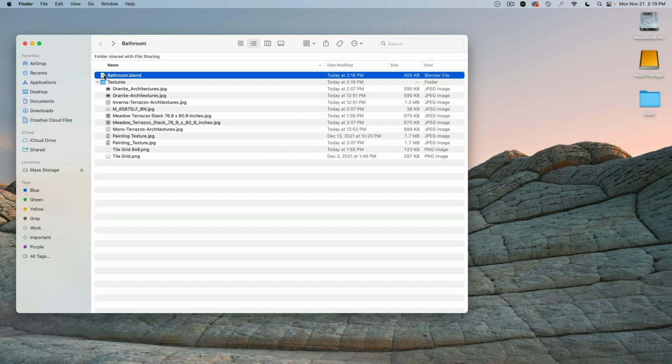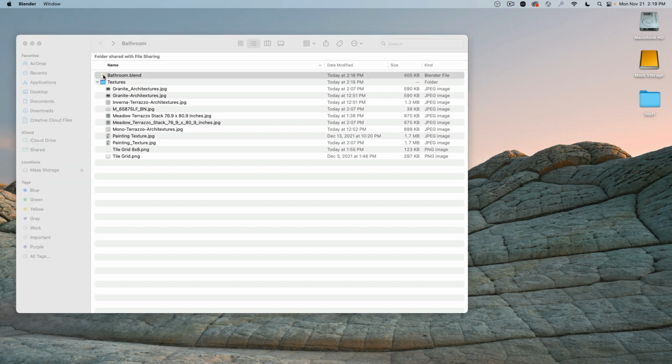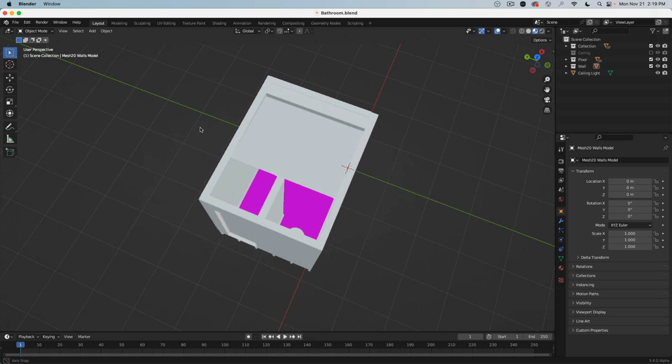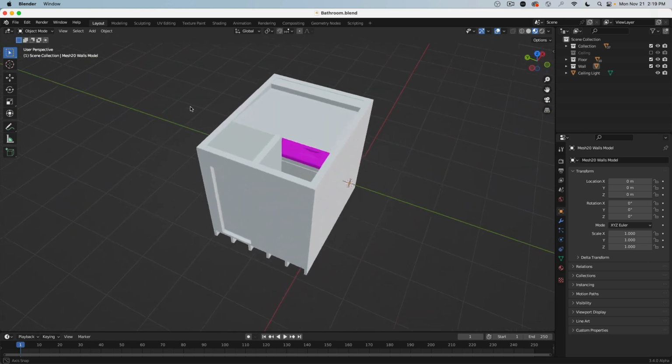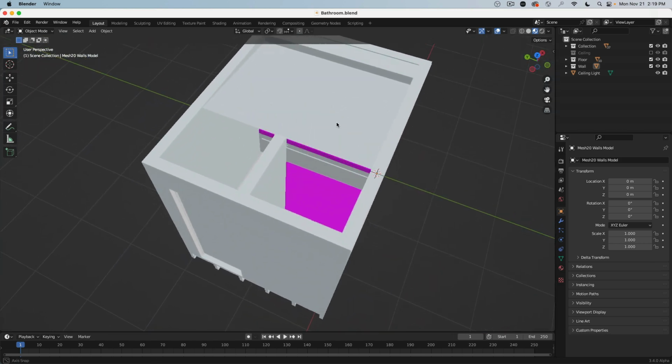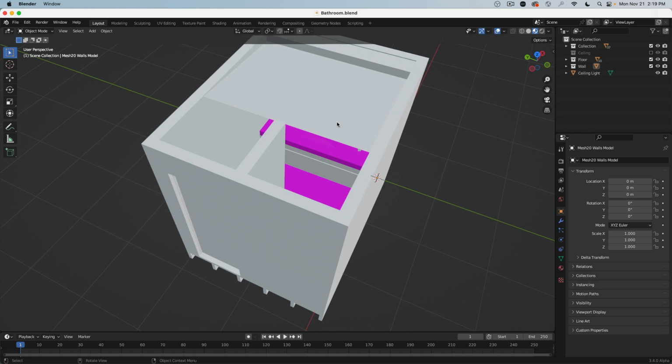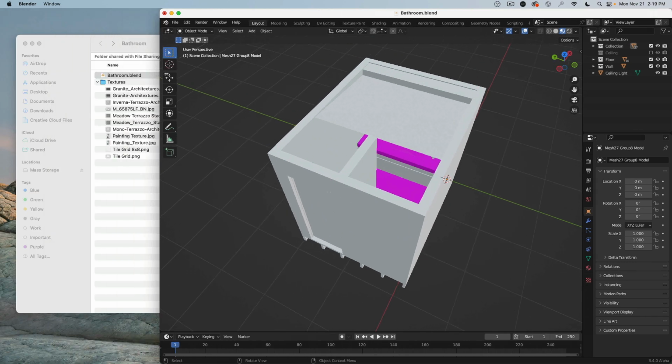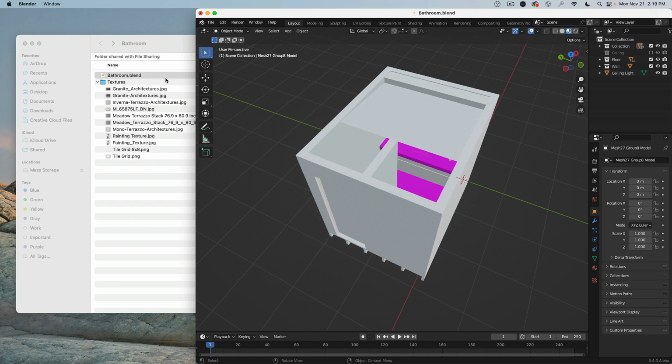When I now go back to Blender and start it, it's actually important. Whoa, look at that. You see, some things are kind of like magenta. And that is actually a warning sign that a material or texture got lost. So this is actually a very easy fix. Now you keep in mind, we have now here this texture folder.